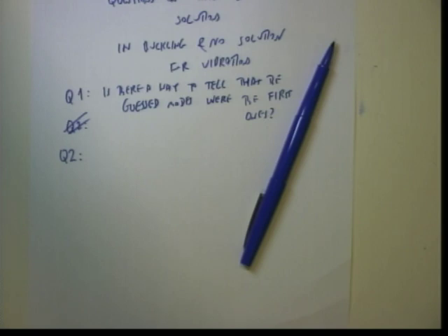Can you speak louder? Students said whether it is applicable to infinite degrees of freedom or to 1 degree of freedom. So we have a beam. Beam is an infinite degree of freedom system. No, this problem, the beam cannot be treated as a 1 degree of freedom system. For a beam there is a governing differential equation.